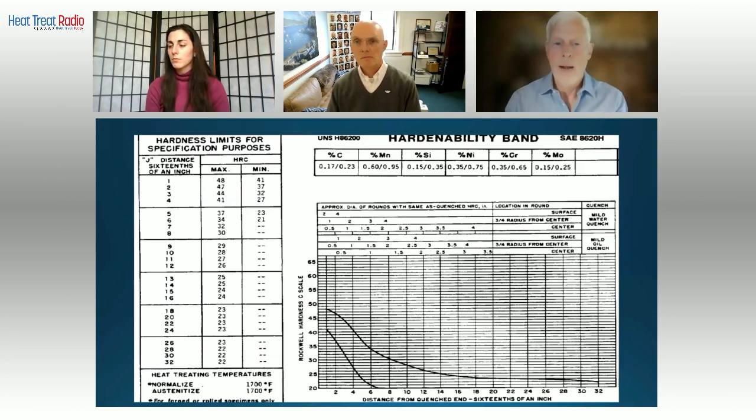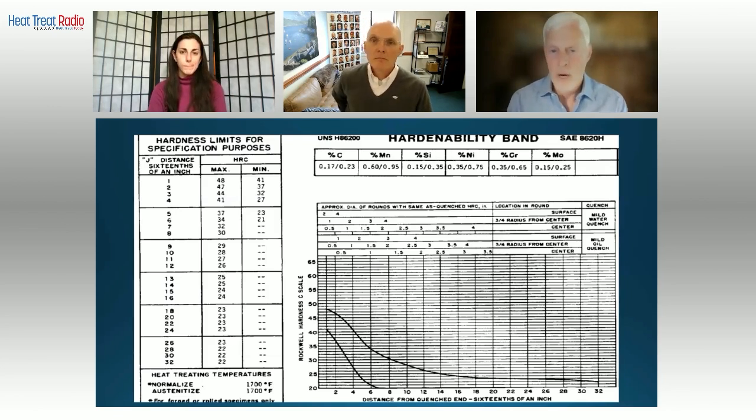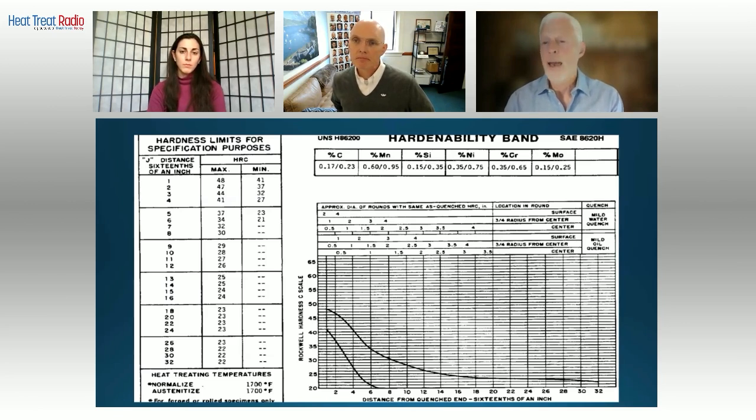Now, to those who are not involved in high volume production, where they do not have control of the source of the material, this chart remains something that is usable. So if you are running a job shop, let's say, or you're running shorter term things, and you don't necessarily have furnace load sizes of parts, then the key there is to be able to mix and match things into specific processes.